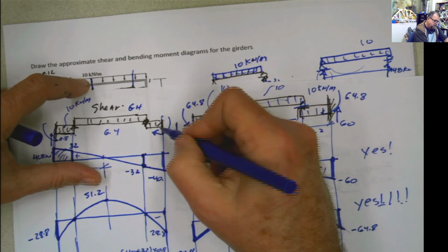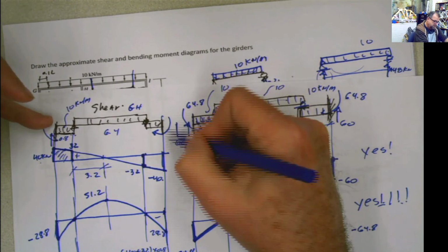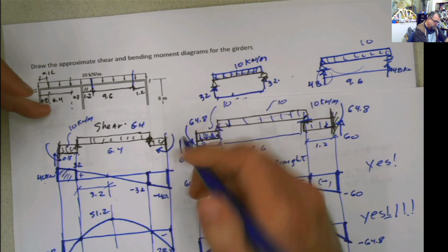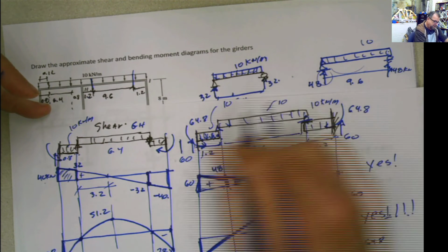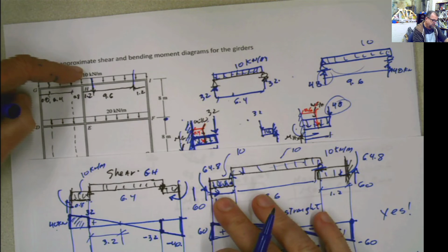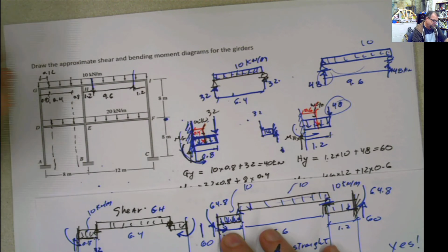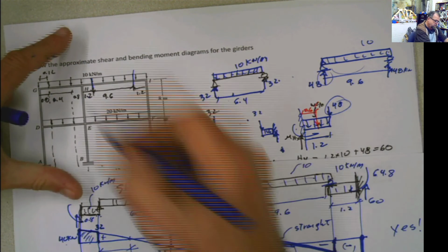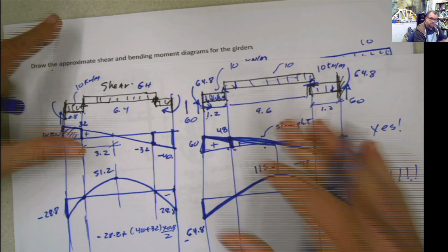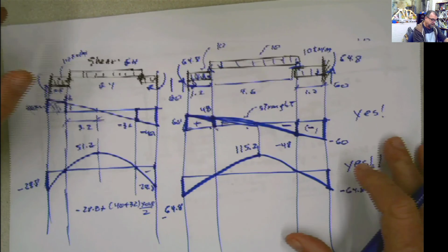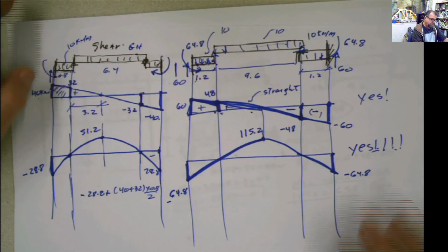So you can do that moment of the column at the joint. Similarly, you're going to have the two reactions. You're going to have a reaction here of 40 kilonewton from this end, and a reaction here of 60 kilonewton, meaning these two reactions are transferred down as 100 kilonewton to this column, which perfectly coincides, by the way, with tributary area if you start applying the principle of tributary area.